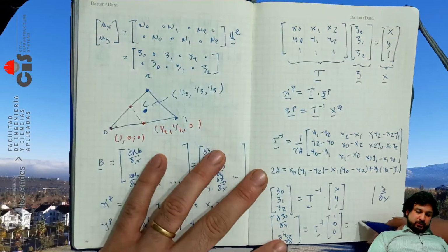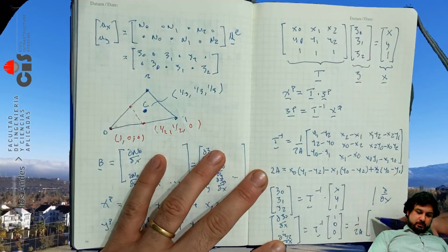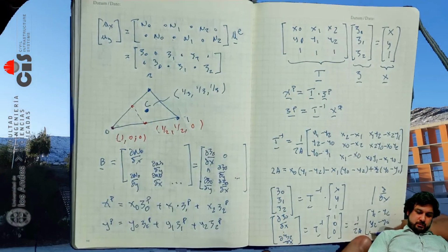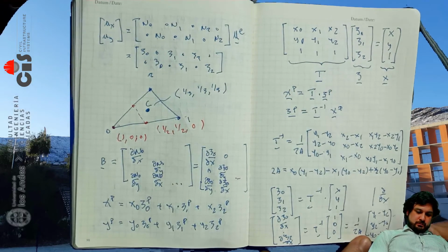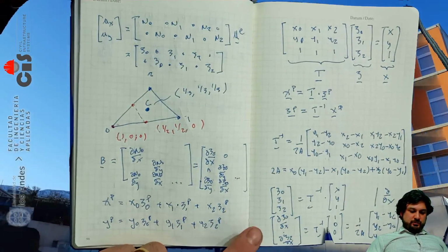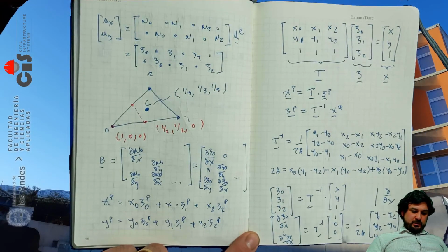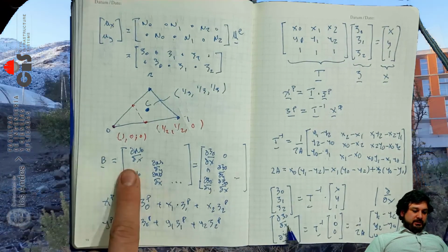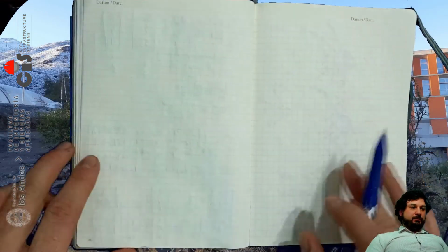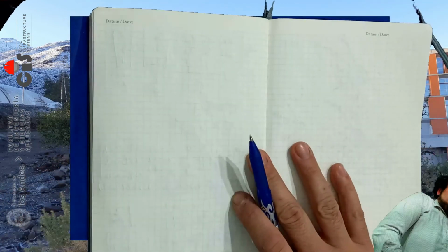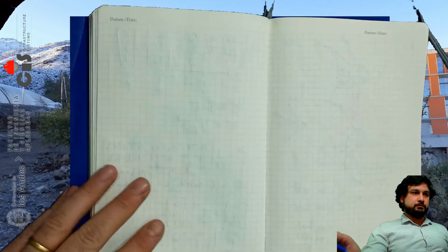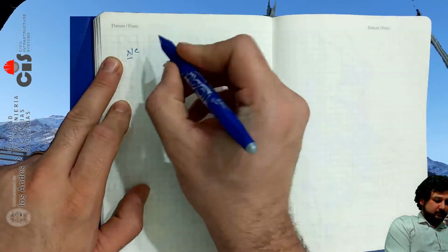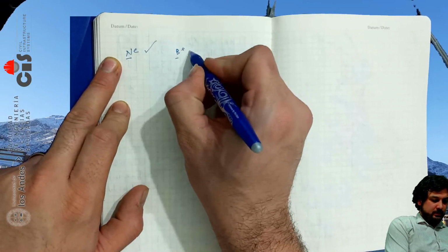So it's going to be 1 over 2A, y1 minus y2, y2 minus y naught, y0 minus y1. So on and so forth for the derivative with respect to y. It's going to give us that second column. So that's great. We have these derivatives. So now we can write what the B matrix is. So we have the N matrix. We have the B matrix.